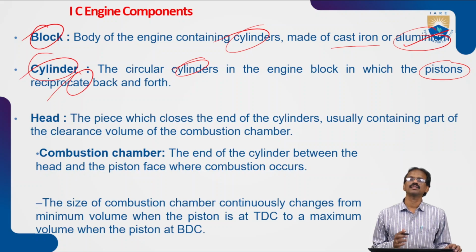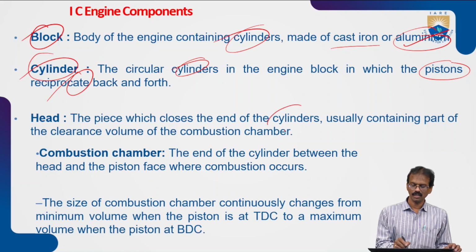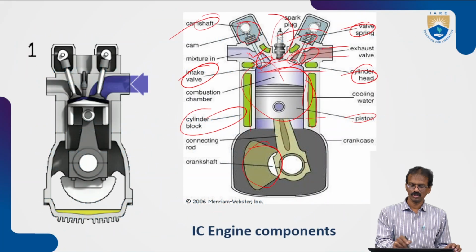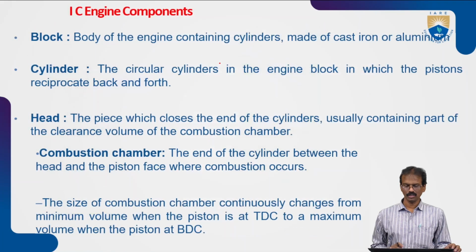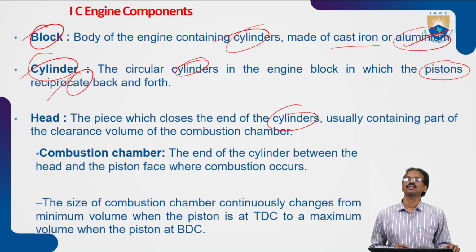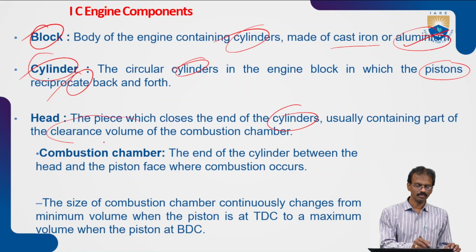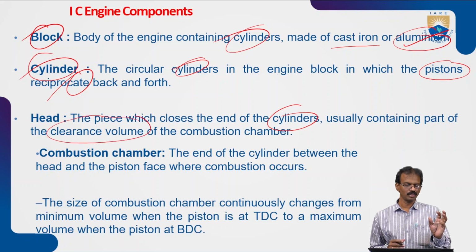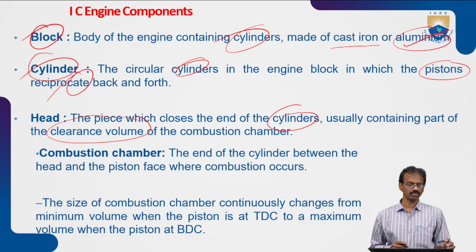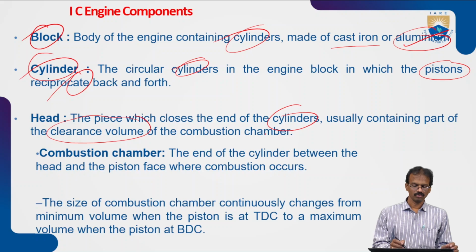Next one, the head. The head is the piece which closes the end of the cylinder. This is the head portion, you can see. It closes the end of the cylinder. Usually it contains parts like the clearance volume. In the compression stroke, all the charge will be collected in the clearance volume before combustion. It is the top of the cylinder head.